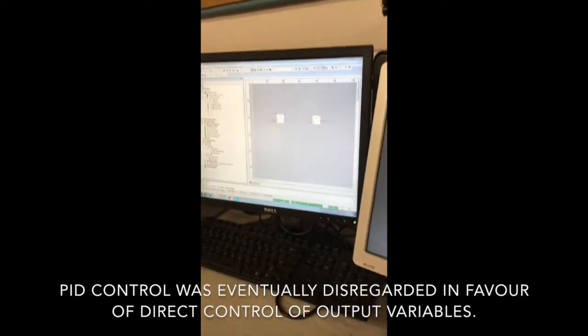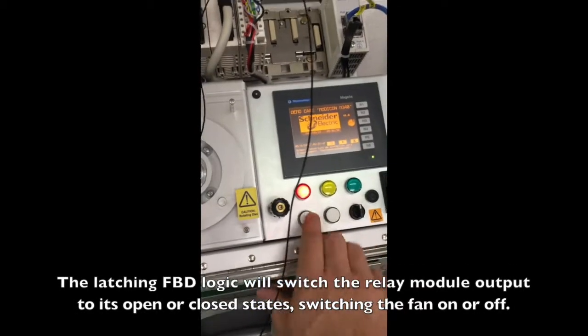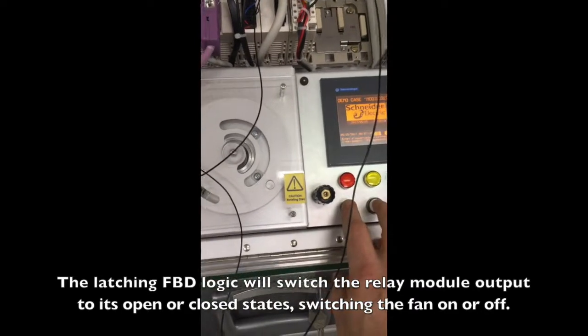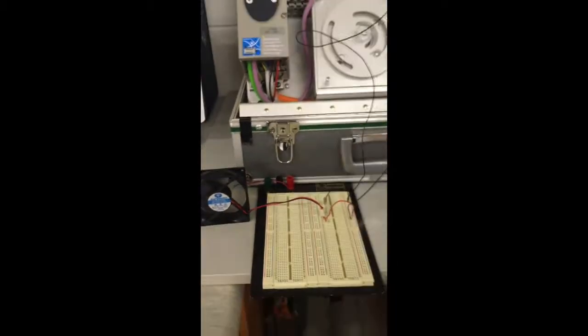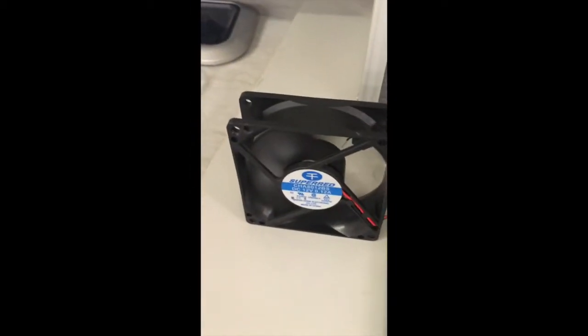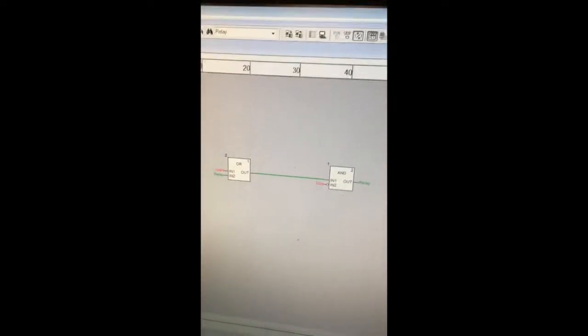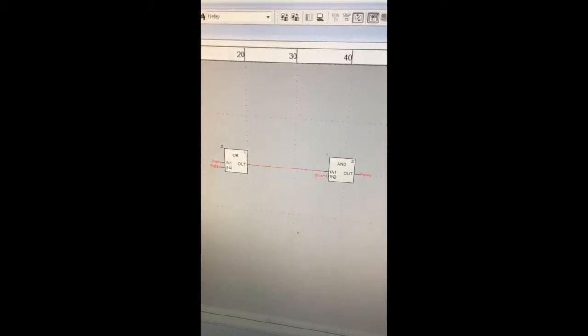This is currently loaded and open, and it's linked to these two positions on this relay module. As you might have heard, as I switch that on, we do receive our necessary 12 volts there to provide voltage to the fan, and our latching circuit is also functioning as intended. Now if we use our off button, we see that it goes off, and also that our latching circuit is now being deactivated.